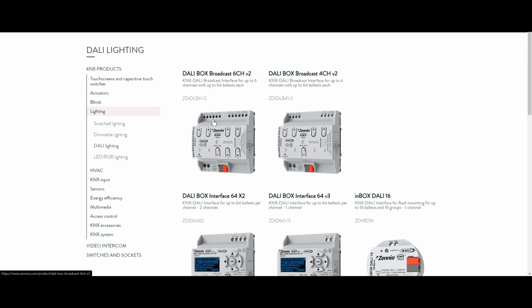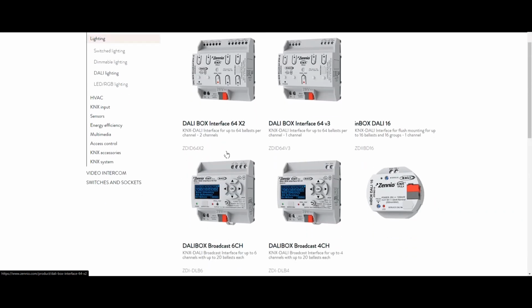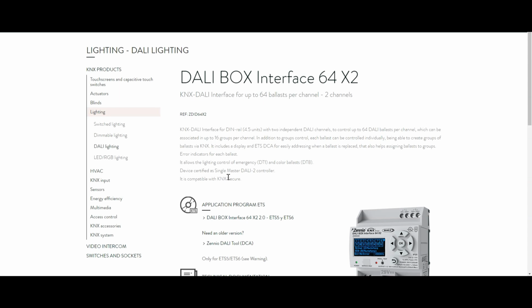That's huge, you know. And when we're looking at simplicity, like I've said previously, there's no configuration, the wiring is fixed, so you can tell the electrician just to wire the switching groups, and that couldn't be simpler. And you still get all the benefit of the DALI with reporting and all that. Not ballast control, but you know, indication of faults and stuff like that as well. So they've also got a range of 2-channel and 1-channel gateways. The beauty of these is they can be configured on the front of the gateway, and these are DALI 2 certified, and they're KNX secure devices.